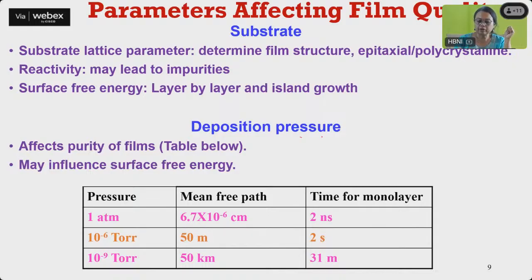But the main effect of the deposition pressure is on the mean free path. What is the mean free path? The mean free path is the distance traveled by any atom in the given environment before it collides with another atom, or the time it takes before it collides with another atom. At 1 atmosphere pressure, the mean free path is not even in microns, it is about 10⁻⁶ centimeter. Okay, very small, no?